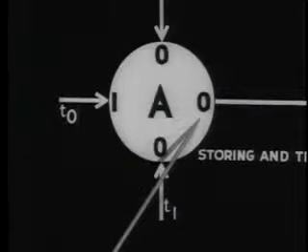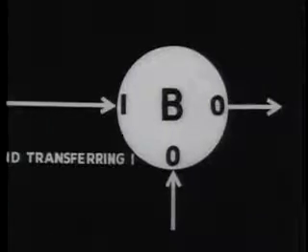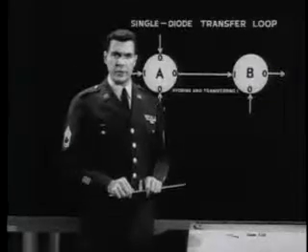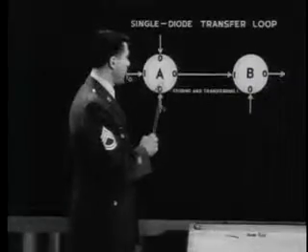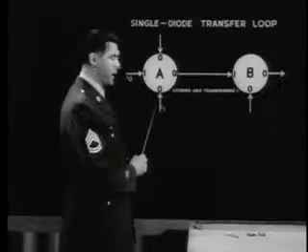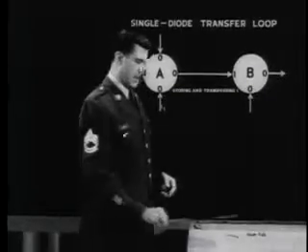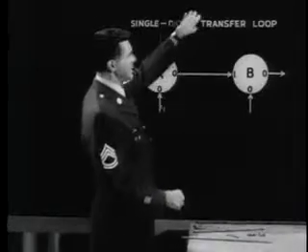And, as the diagram indicates, whenever the core is cleared to 0, an output occurs, switching core B to 1. But this means that either one of the dot inputs can bring about a transfer of the bit from A to B, the bottom one or the top. Tighter control is frequently necessary.